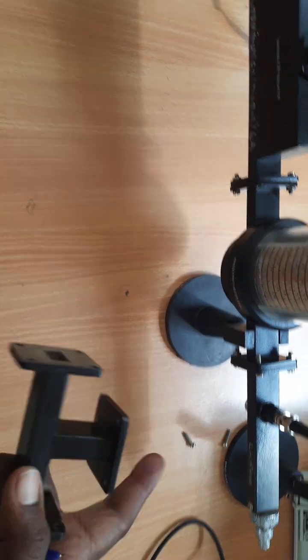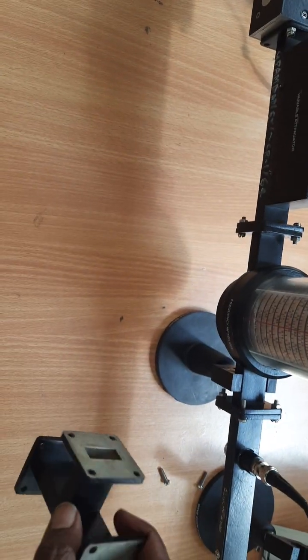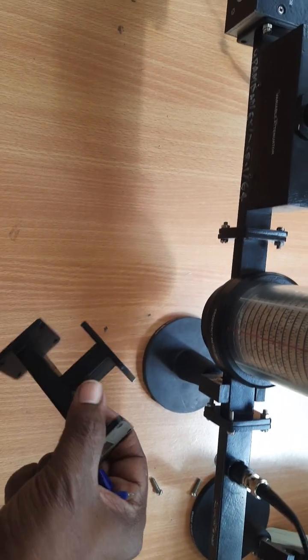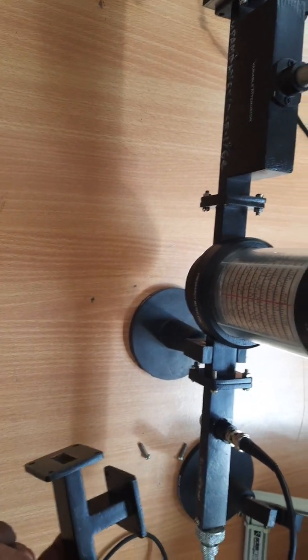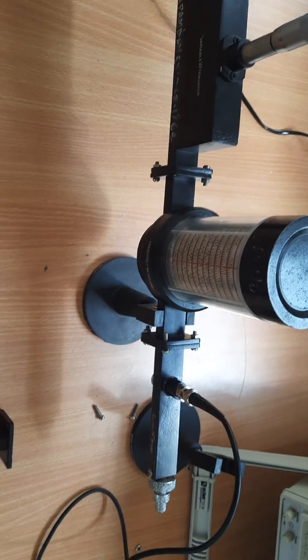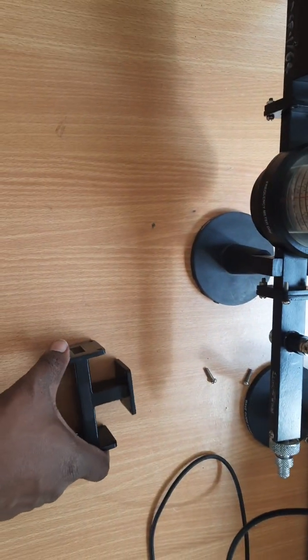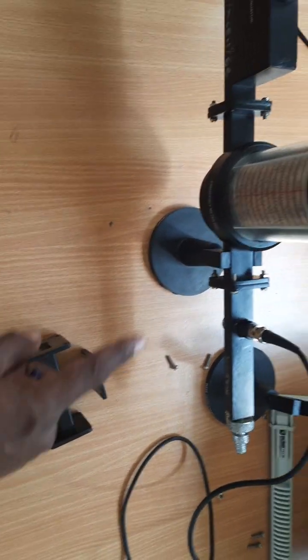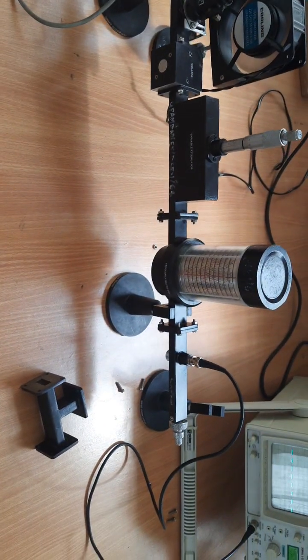I am connecting the E arm as the input, and now I am measuring the output at port number 1 or port number 2, one of the ports. So it will give me a coupling factor. So just wait for 1 minute. I will disconnect your detector mount and connect your E plane T to your microwave test bench. So we will wait for 1 minute.